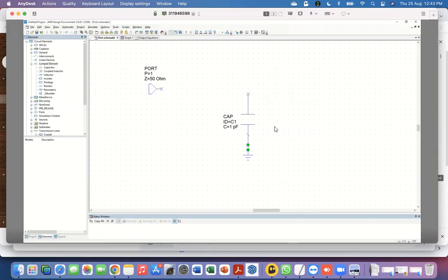And for some circuits, we do use lumped elements. They do exist in the sense that you can buy a capacitor which is supposed to work at the microwave frequency range. It's just that they are not ideal. Everything we do here in this circuit domain gives you the ideal response. And that's often the starting point of designing any microwave circuit, that you look at the idealized response and then you worry about the fact that it's not really ideal, and in most cases, it won't matter.